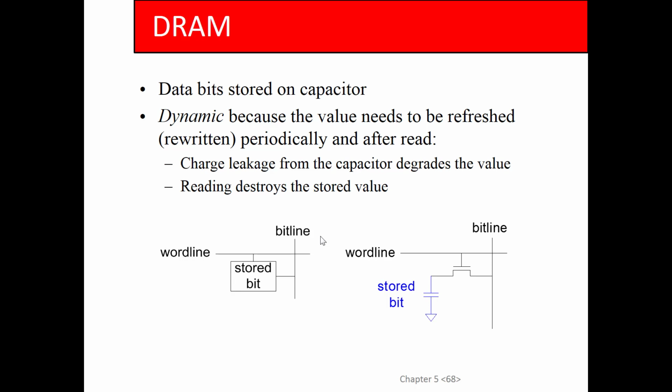That represents your rise and fall time if you're doing digital. And if you have a bunch of gates connected in series through a critical path, you have to pay for that rise time all the way through the digital circuit. That gives you your propagation delay, right? So you don't want capacitance.